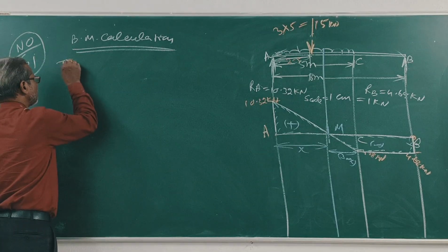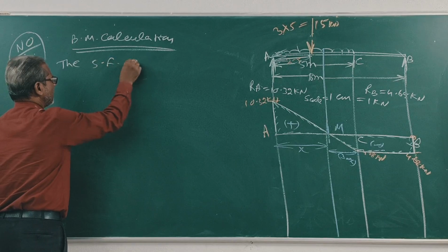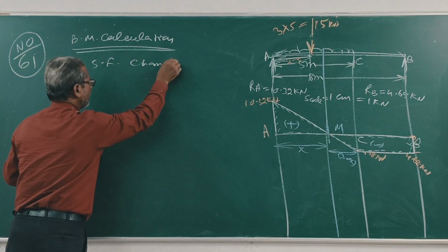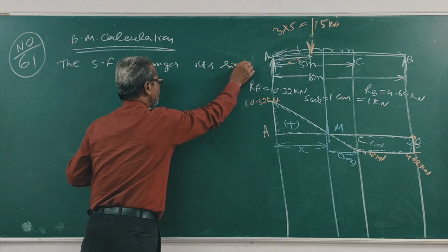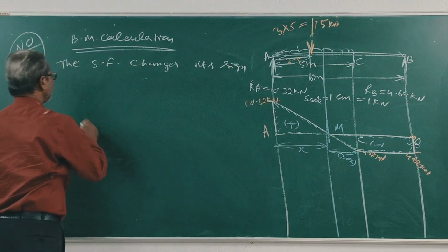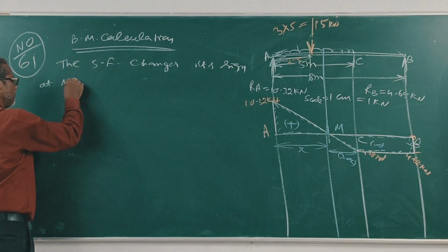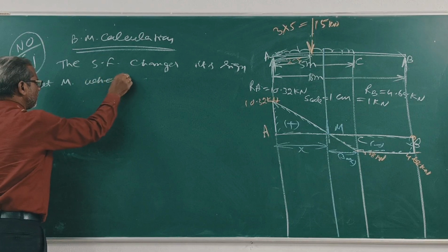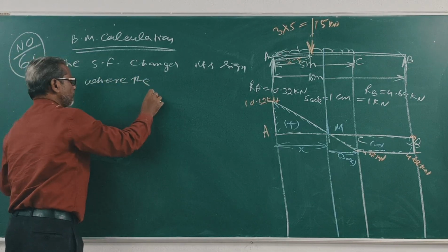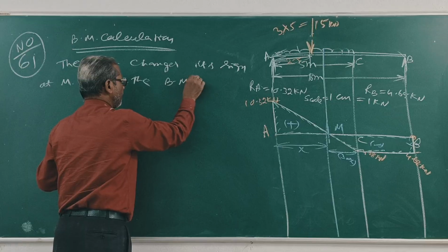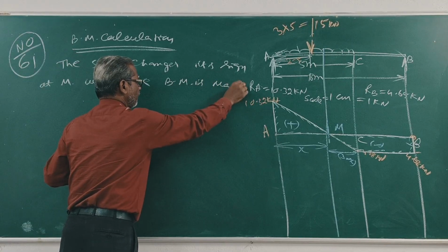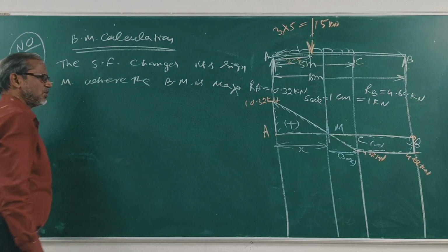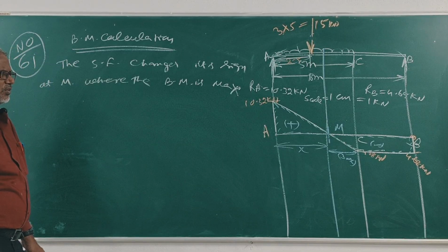The shear force changes its sign at M, where the bending moment is maximum. Clear? First find out the value of x.